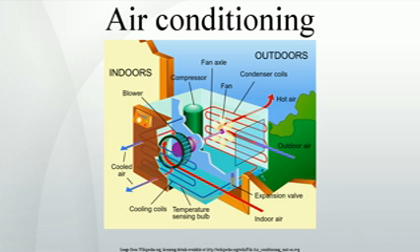Most ductless, split-system air conditioners still typically provide cooling to a single room or interior zone, just like a window air conditioner or PTAC. But more powerful outside units are becoming more and more available, supporting cooling of ever more interior zones. Advantages of the ductless system include smaller size and flexibility for zoning or heating and cooling individual rooms. Flexible exterior hoses lead from the outside unit to the interior one. These are often enclosed with metal to look like common drain pipes from the roof.